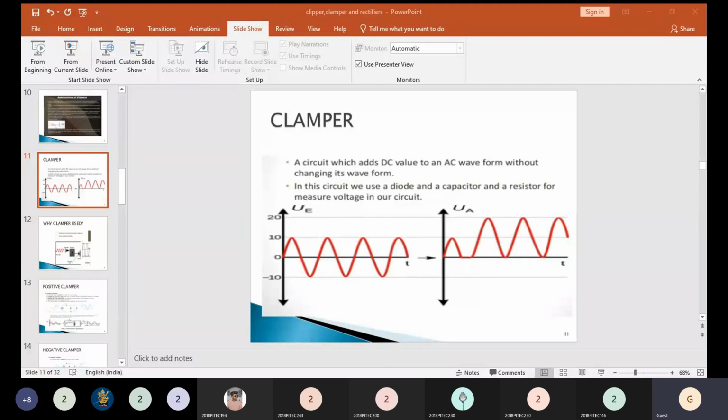So this Im value is substituted in the average value formula. The average value formula is Im divided by pi, right? So your answer is Vm divided by pi times (RF plus RL). So option B is correct. Okay, moving to the third question.